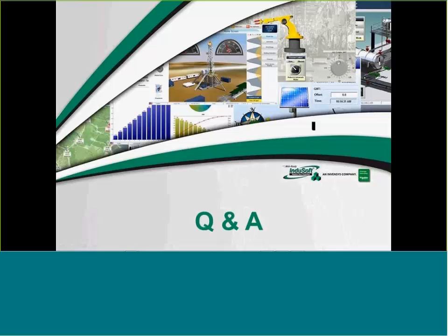Okay. Next question that came in is, what is SYSMAC Compolet? I've seen it mentioned but not explained. Great question. So there's technically two products that I'm lumping together and calling SYSMAC Gateway. SYSMAC Gateway is the runtime engine, and CX Compolet is a .NET library and .NET class that InduSoft Web Studio also uses for communication. So what is actually deployed is CX Compolet with SYSMAC Gateway. I am referring generically to the product as SYSMAC Gateway.